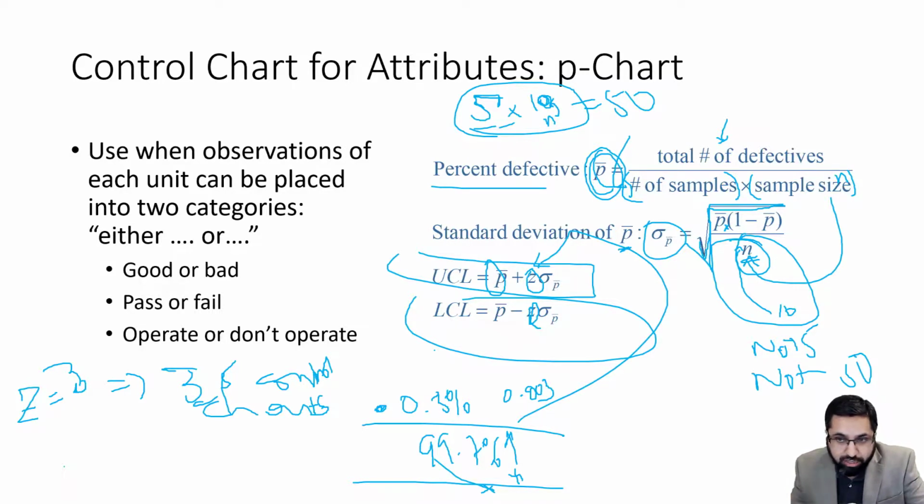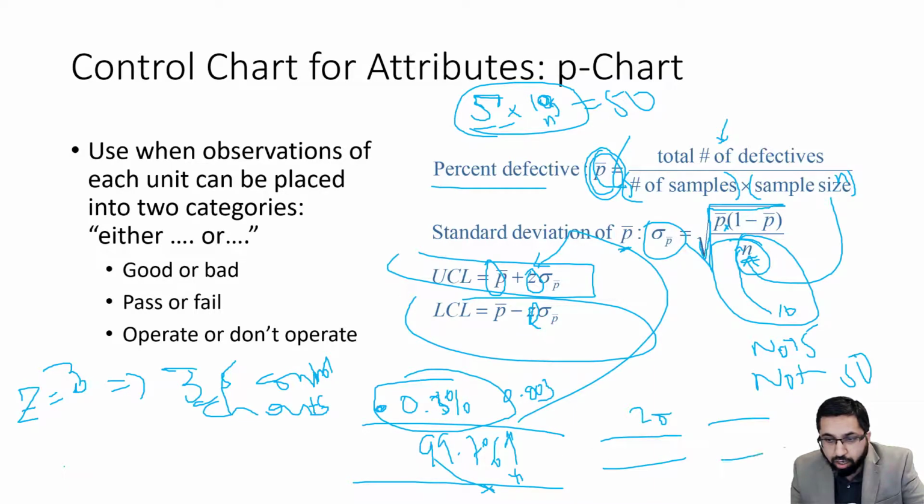The control chart says something is going on, you go investigate, and nothing is going on. With 3 sigma control charts, you only get these false positives 0.3% of the time, which is relatively rare. That's why we like 3 sigma control charts. However, depending on the situation, you might go for 2 sigma or 4 sigma control charts, and all the 2 sigma, 4 sigma, or 3 sigma is doing is changing the probability of a false positive, because you want to control that.